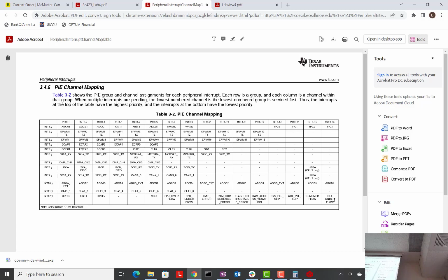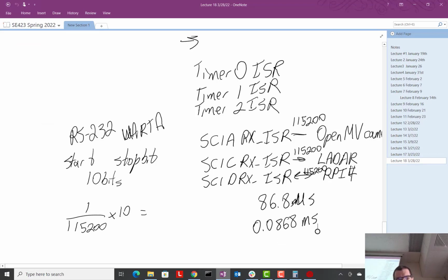Just like we've set up, above, timer 0's interrupt, ADC A's interrupt, and all that kind of stuff, I set up these 3 interrupts so that I can post them, tell them to be called in software only. Remember, what did we say? Hardware interrupts. It was always something in hardware that caused that function to run. This thing I'm calling a software interrupt, you've got to force the interrupt in software. And so to do that, you're going to see when you get done with exercise 3, the way you do that is with this call.